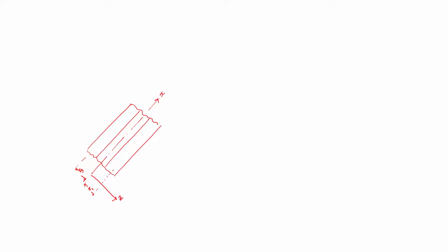And you can appreciate here that suppose the mid surface strain is epsilon x naught. For the middle layer, it is epsilon x naught only. I mean, if it is also experiencing curvature, then the strains of the other two will be different. But here it will be same because the reference surface actually passes through this layer itself. Therefore, here it is 0 because Z2 is 0. Is that clear?